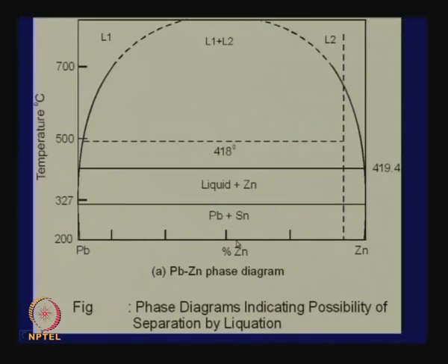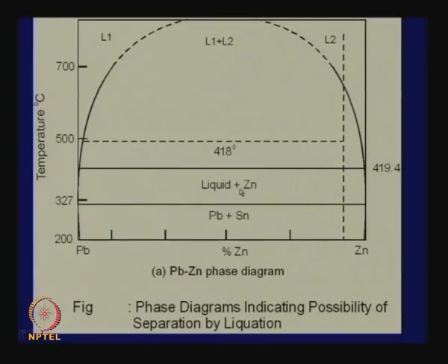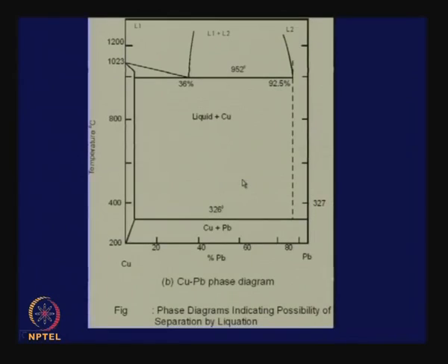Now, in the imperial smelting process, we will deliberately produce that lead zinc alloy by spraying lead on zinc vapors. But there can be situations where you have zinc impurity in lead that can be very easily taken out just by heating the alloy to above the melting point of lead. This kind of principle is evident in many phase diagrams.